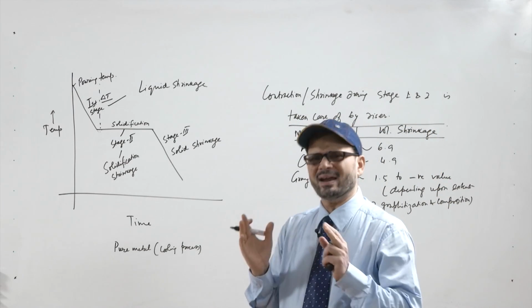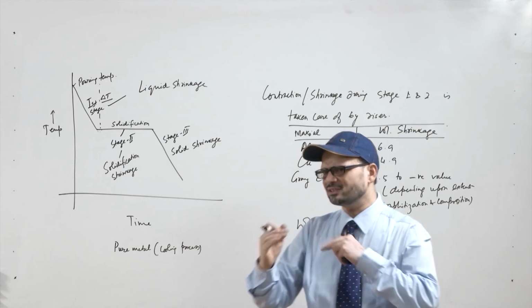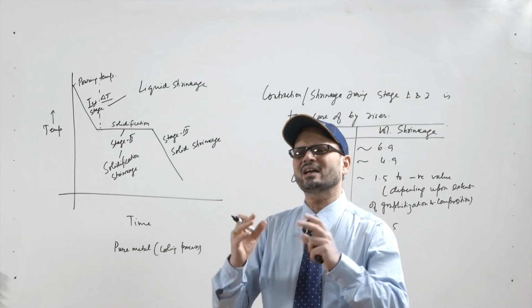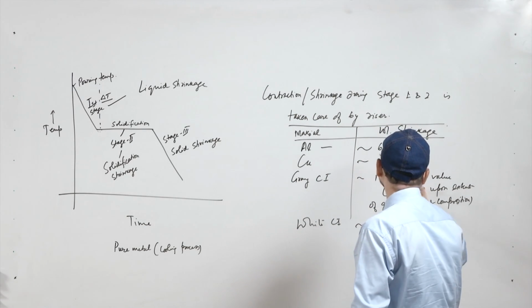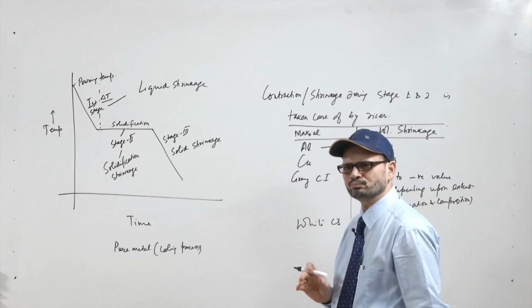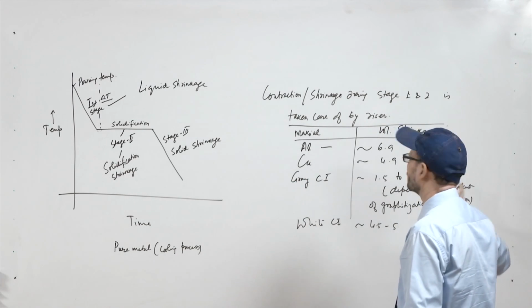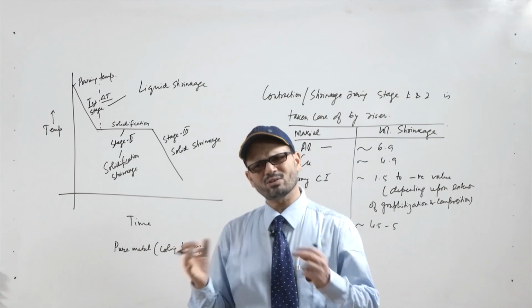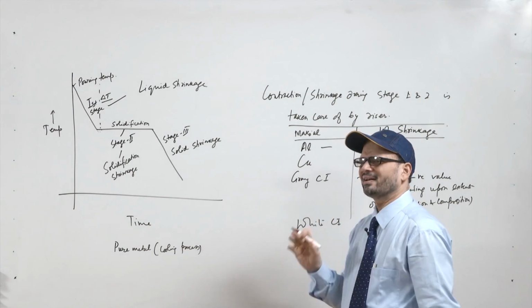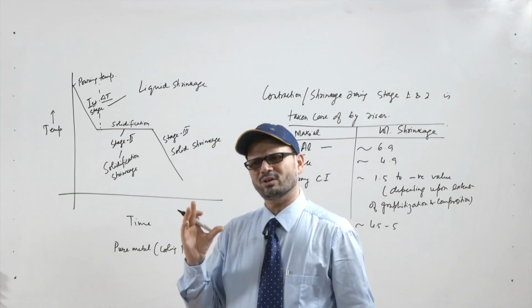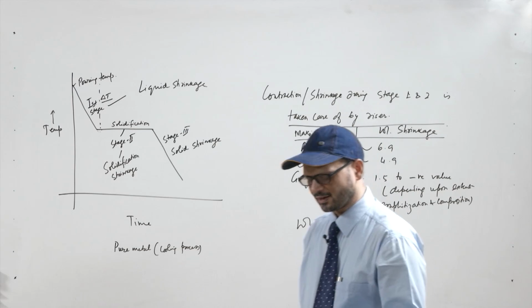So, basically it expands with the formation of this graphite, and because it expands, the volume increases. So, that is why this is very small and sometimes even a negative value. So, sometimes we go for certain cases known as riser-less design, where a riser is not required. Grey cast iron is such a material where the riser requirement is very less because of the graphitization which takes place.